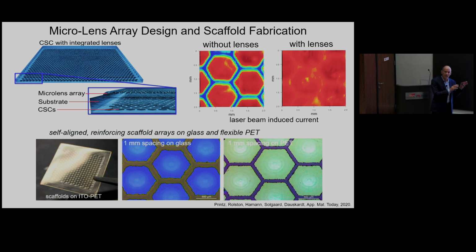And in fact, there was some neat innovation in this area. We realized quickly that it would be better to make the optics first and then put the photoresist on top of the optics and then do the exposure for the photolithography through the optics that we had already made. So we had perfect registry of the optical corrective lenses with the underlying cells.